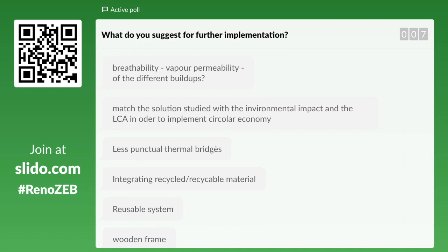We have two membranes on the front side where we have breathability and, for example, UV protection. On the other side, we have a vapor barrier but it guarantees breathability from the outside to the inside. So from the inside to the outside we have a vapor barrier, from the outside to the inside we have high breathability, and this is valuable for us for this type of product.